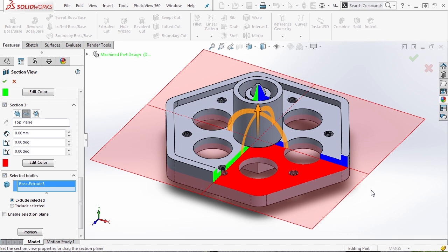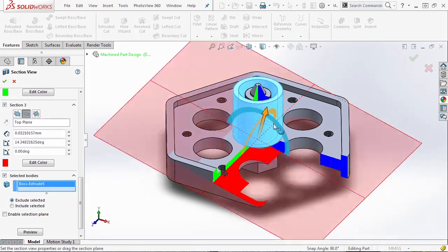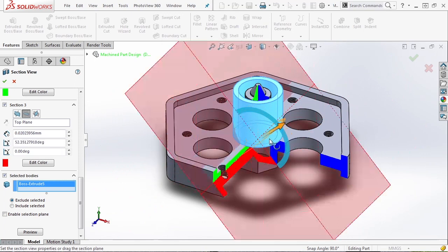So again, this is very handy in multi-body parts or assemblies where you have things like hardware, you have screws, bolts, washers, nuts, things that you don't necessarily want to cut through, or specific details, things that are running through parts that you need to see and you only want to cut away certain sections. So in the past couple versions of SOLIDWORKS, they've allowed us to do that and it's been really handy. Allows you quick selection process in order for making these section views through your components.